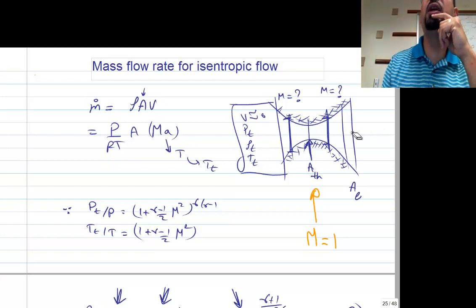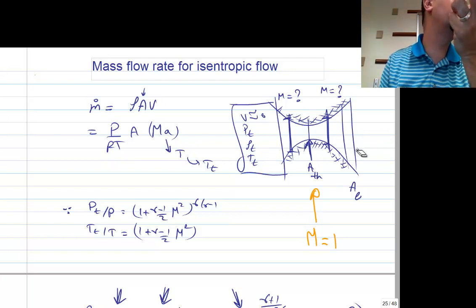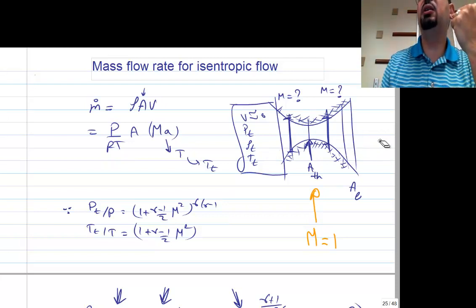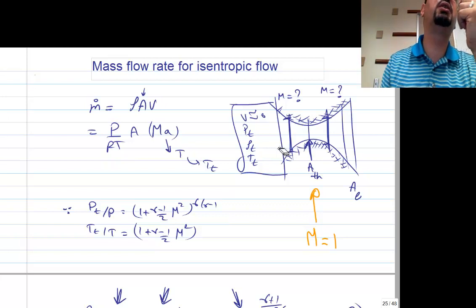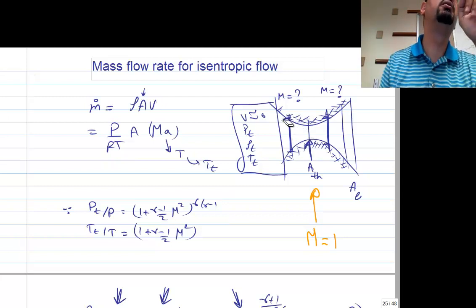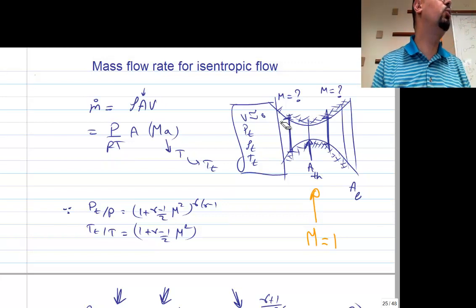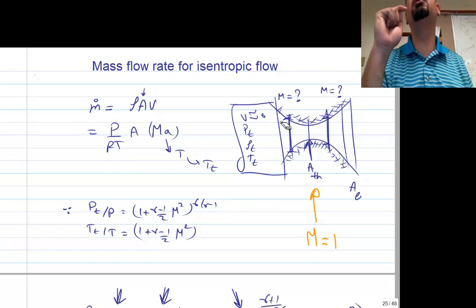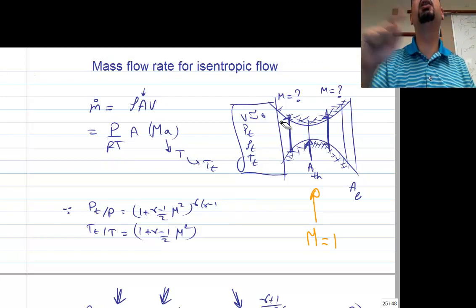But if you see a flow that's not supersonic at the exit, because the pressure is not much, like 100 kilopascal, 101 kilopascal, that's not much, and the Mach number here will not be supersonic, and that throat area is not area star. What is area star then? Well, it's the area that will make the Mach number equal 1 at the throat, at those pressures.